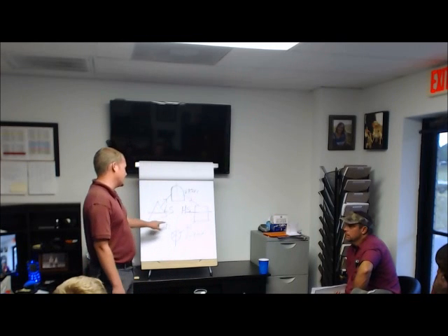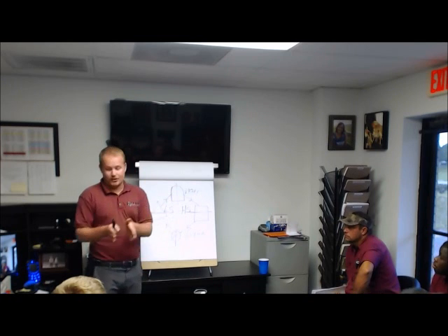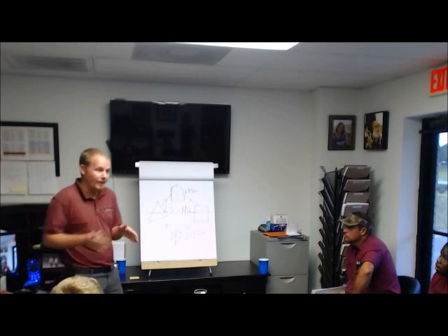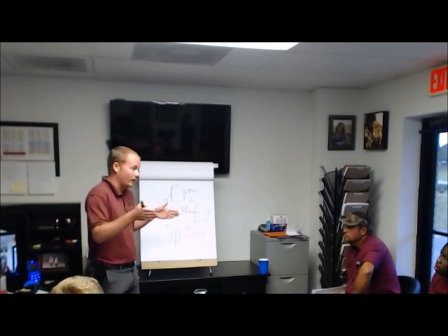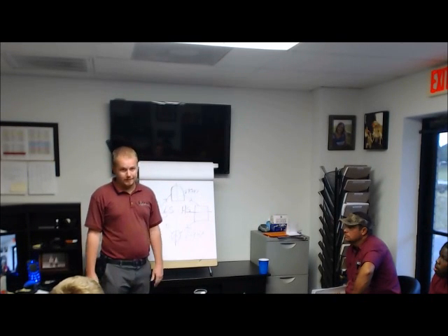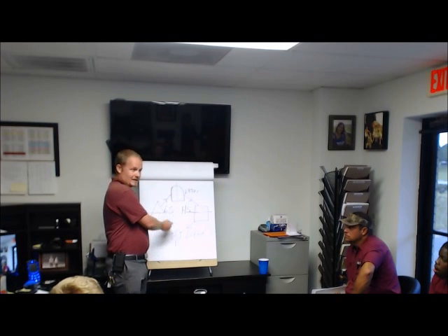But that means that if we can measure a temperature here, we want that to be matching what's on our PT, our pressure temperature correlation scale on our gauges. We want that to be matching saturation because we want to be able to prove that the refrigerant here is in that change of state. Okay? Now, we know that it's flash gas here, meaning it's in the process of changing.